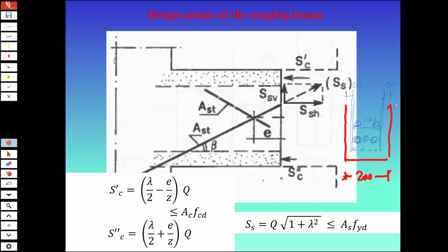But there is a but. If you have to cast in place, then you assume that you are going to vibrate with a poker vibrator. Poker vibrator, the minimum size is 7 centimeters, at least in Italy. So the vibrator does not pass through. Or which are the solutions? Well, vibrate at formwork or use self-compacting concrete, which does not require vibration. Actually, self-compacting concrete was developed exactly, among the other things, to solve the vibration issues in very congested areas.